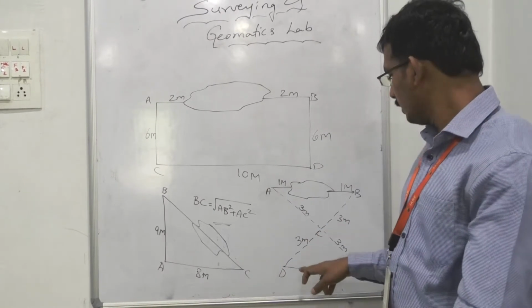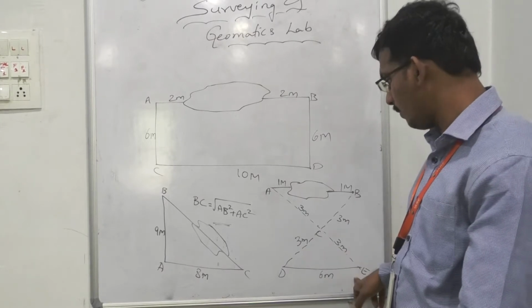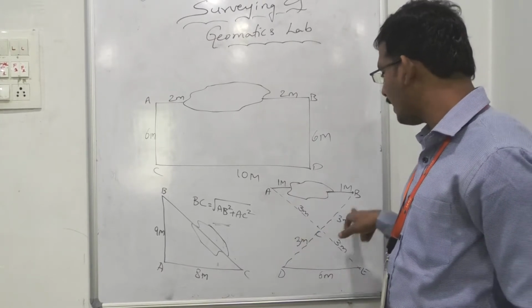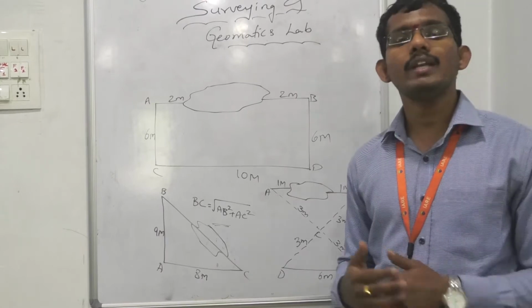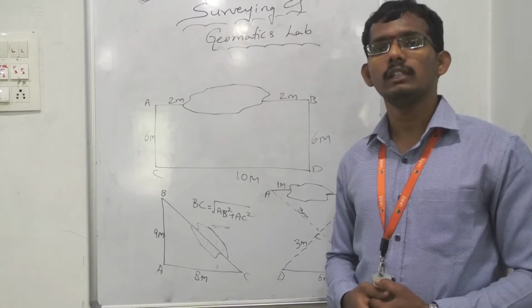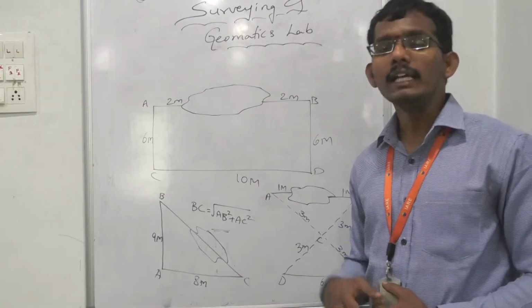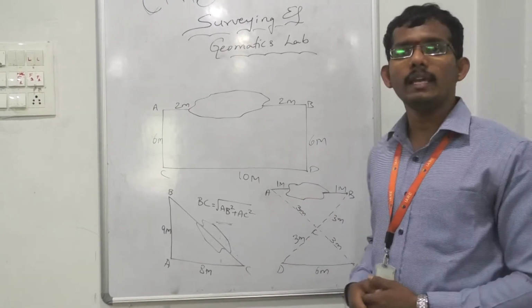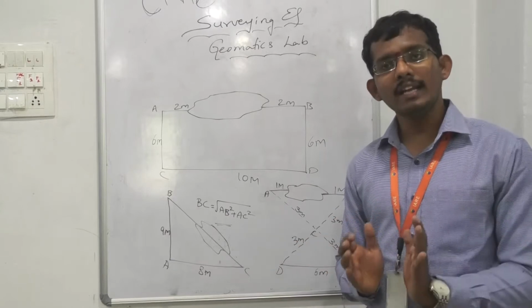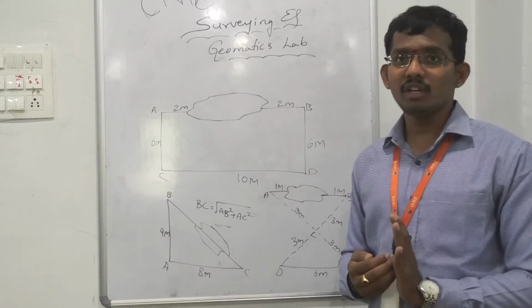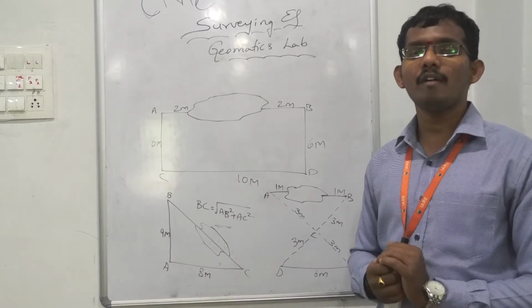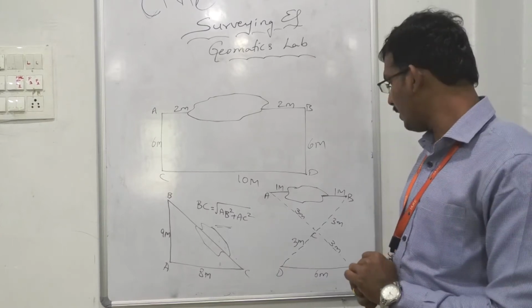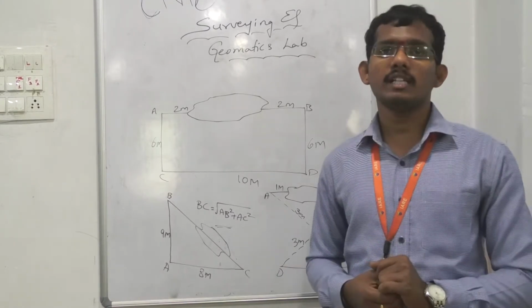Here sides DC and DE are equal, and sides DC, AC and AB are equal. Similarly, when two sides of a triangle are equal, the third side will be similar. So here length DE is equal to length AB. AB lying as an obstacle, we can measure indirectly by the principle of similar triangles, so that AB is equal to DE is equal to 6 meters.